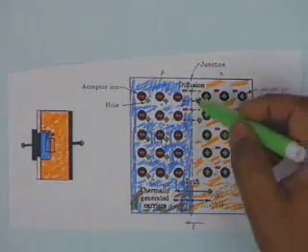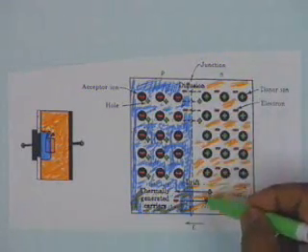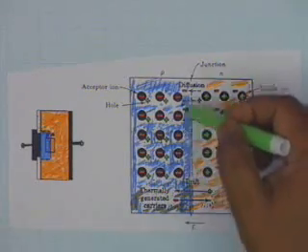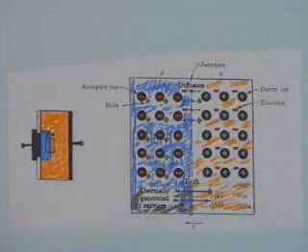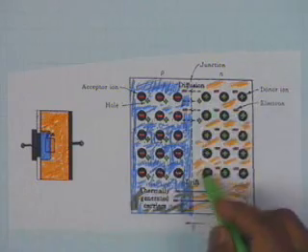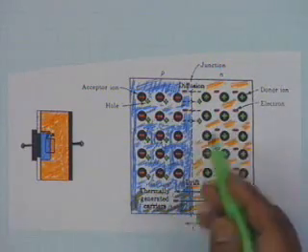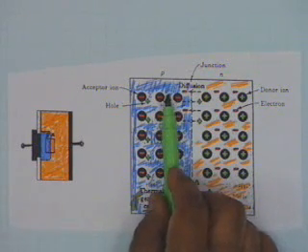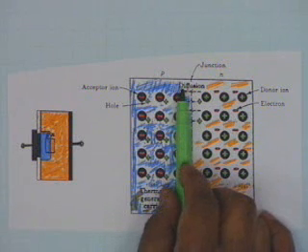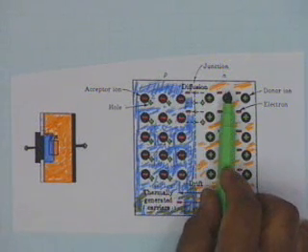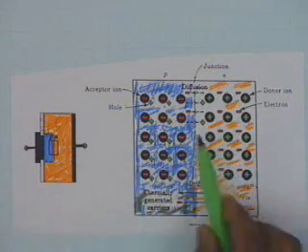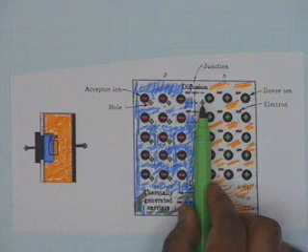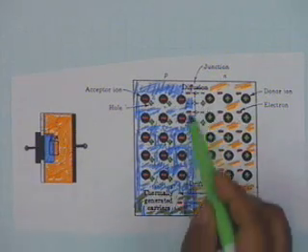But look at the situation. There is a profusion of electrons in this region, there is a profusion of holes in this region, and they are brought close together, and therefore by diffusion, the right hand side is full of electrons, the left hand side is sparse in electrons, therefore electrons diffuse from the n-type region to the p-type region. Similarly holes from the left hand side diffuse into the right hand side, and as soon as they cross the barrier, holes, for example, they meet electrons, and therefore they recombine. Alright, we have shown some of them here.